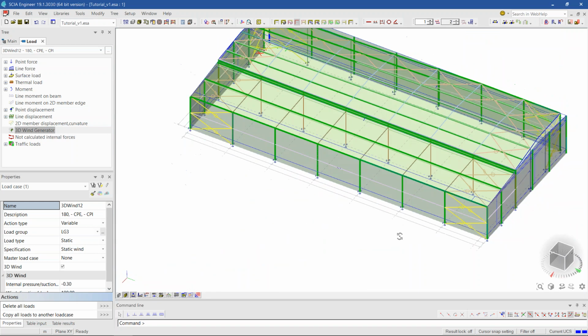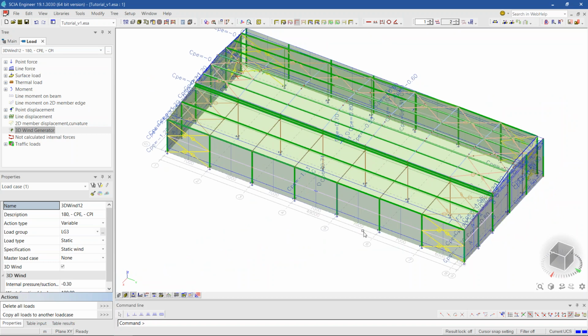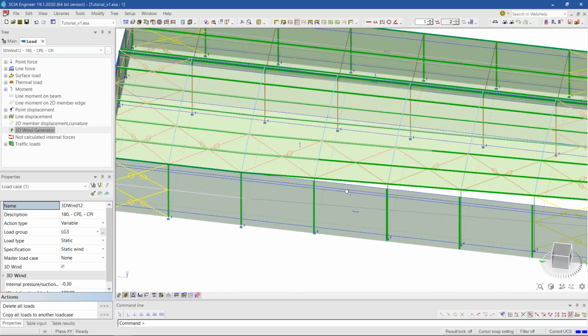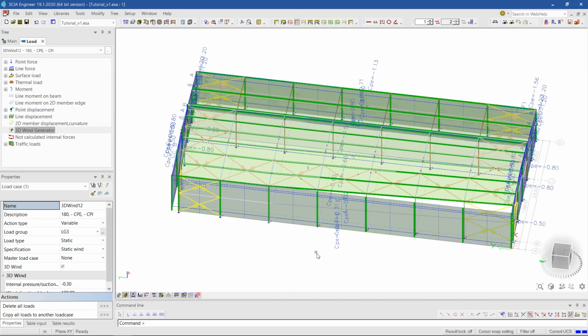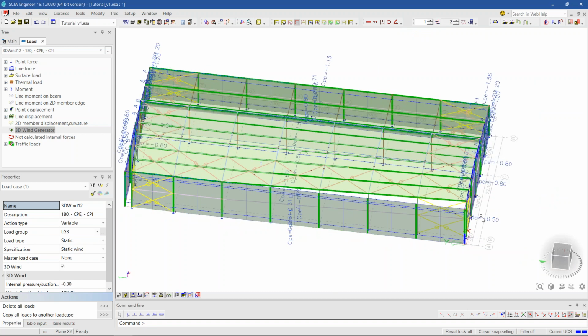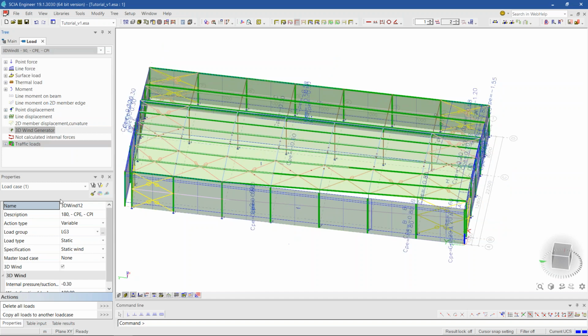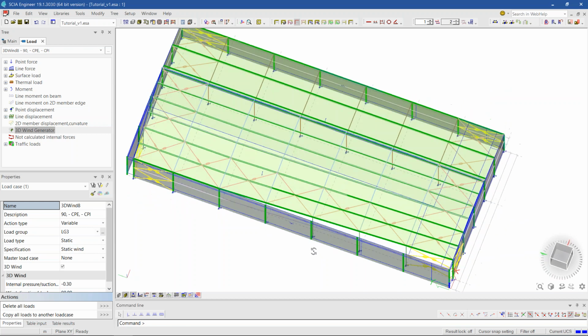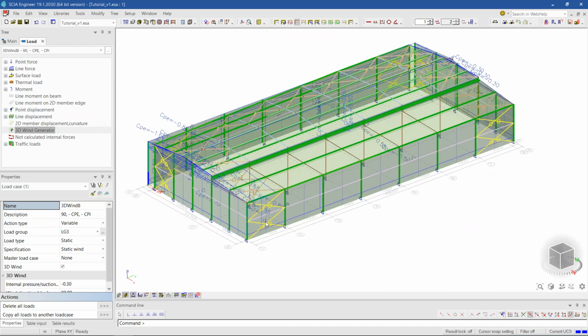So I think this is something that I used in order to avoid having too many problems with load panels that are, let's say, at an angle to each other, which means that by default, they will be considered as separate walls. So when I have wind from this direction, I think it's 90, I would have had the zones A, B, and C also here, like A, B, and C, because this is not a straight wall.